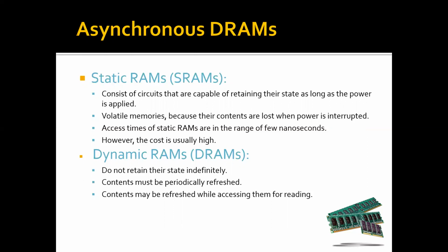If you compare with dynamic RAMs, they do not retain their state indefinitely. This doesn't mean that static and dynamic RAM are not both volatile. However, as long as the power is there, static RAM will retain its state. But dynamic RAM, even if the power supply is there, will lose its charge, as capacitors are used over here.